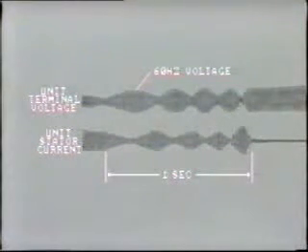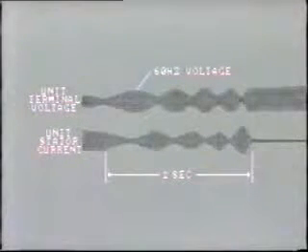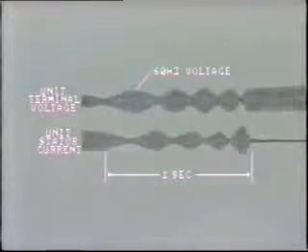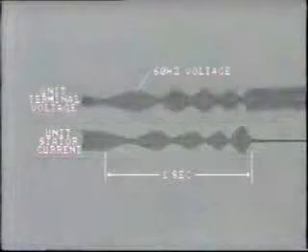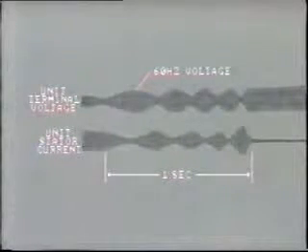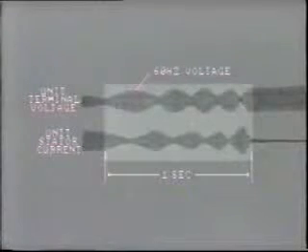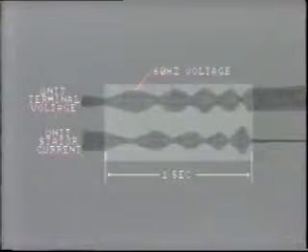Oscillations in voltage and current show up as envelopes superimposed on the normal 50 or 60 hertz voltage or current. This example shows generator terminal voltage and stator current recorded on a conventional fault recorder in the power plant. In this case, the unit lost synchronism and began slipping poles after a major tie line was opened. The recording shows about 1 second of the disturbance.